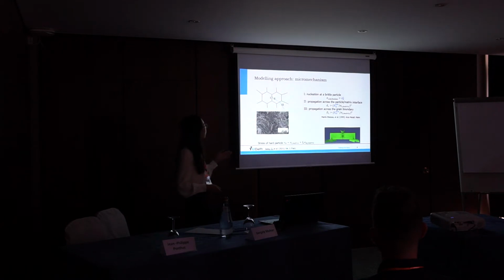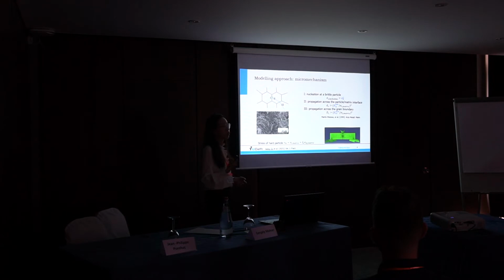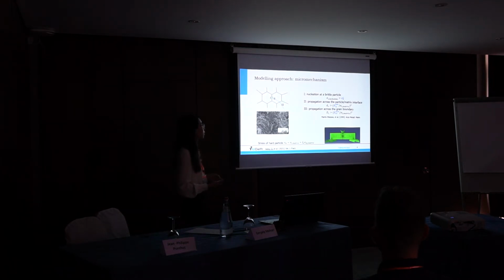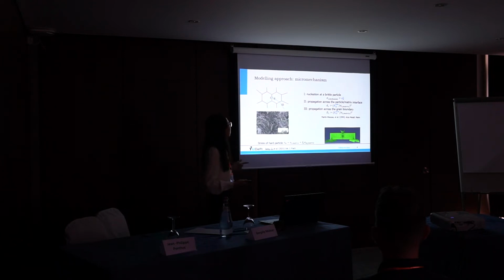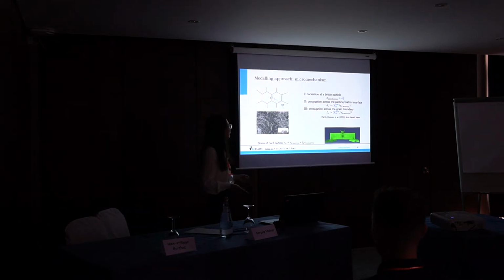All three events are based on stress criteria, and there are two types of stress used in the equations. One is the stress in the matrix, which is the stress distribution in the matrix, calculated from the finite element analysis of the fracture test.